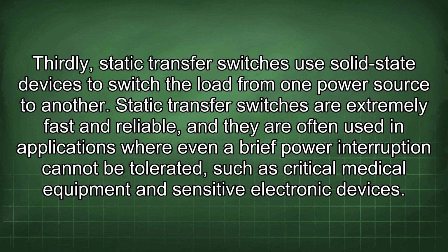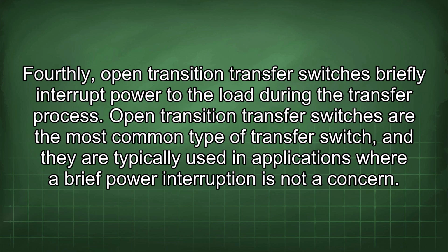Thirdly, static transfer switches use solid-state devices to switch the load from one power source to another. Static transfer switches are extremely fast and reliable, and they are often used in applications where even a brief power interruption cannot be tolerated, such as critical medical equipment and sensitive electronic devices. Fourthly, open transition transfer switches briefly interrupt power to the load during the transfer process. Open transition transfer switches are the most common type of transfer switch, and they are typically used in applications where a brief power interruption is not a concern.